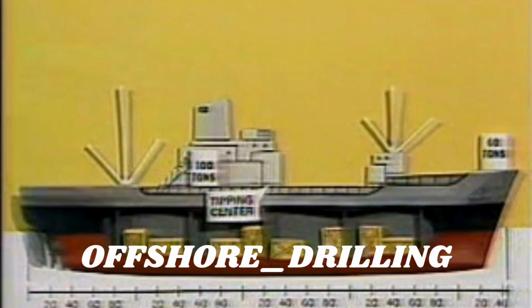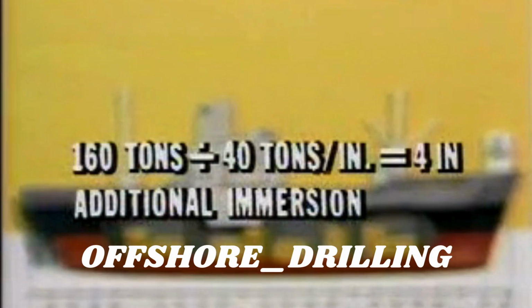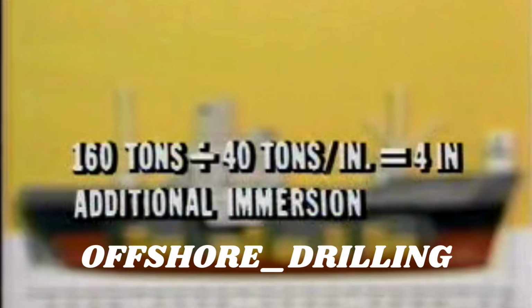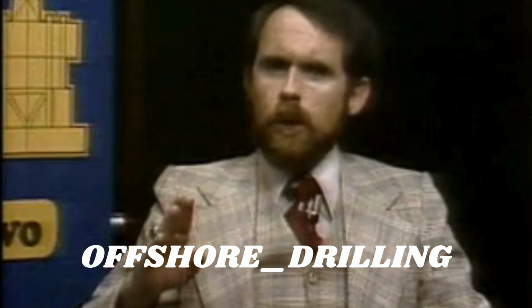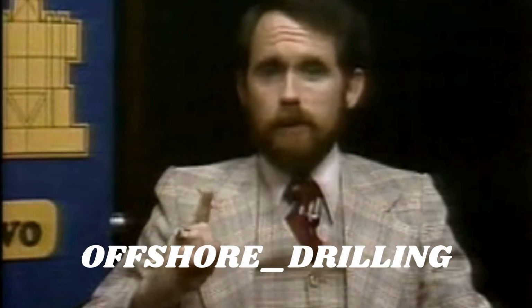The final mean draft will be the original mean draft plus, for loading, the added weight divided by the TPI, or tons per inch immersion. The added weight is 160 tons, and this is divided by 40, the TPI, which gives us 4 inches additional draft due to loading. So the final mean draft is 14 feet 4 inches. Now we would go to the deadweight scale and get the MT1.